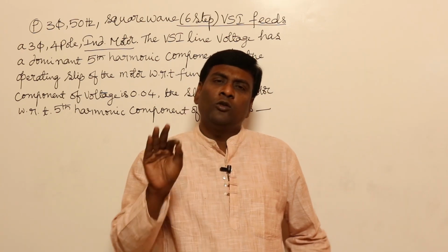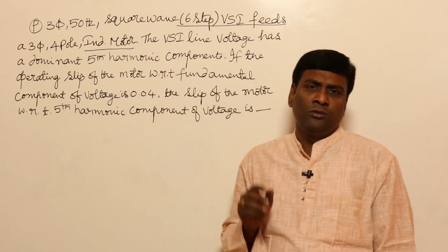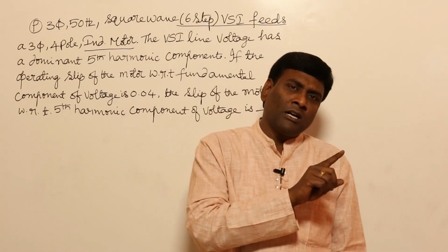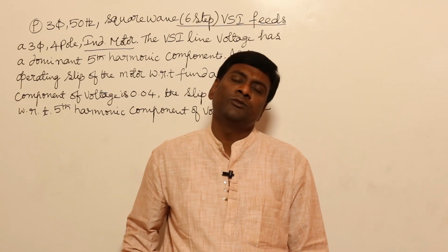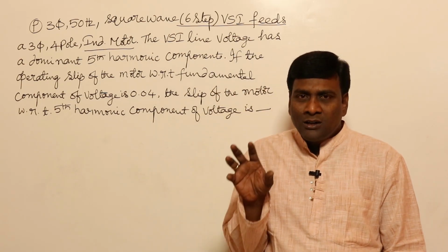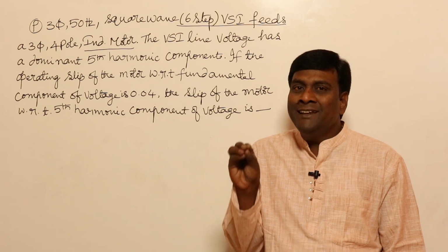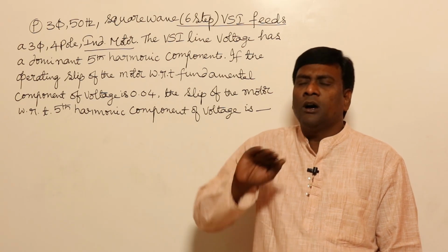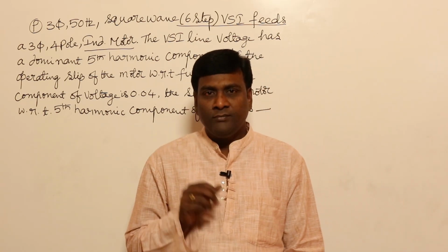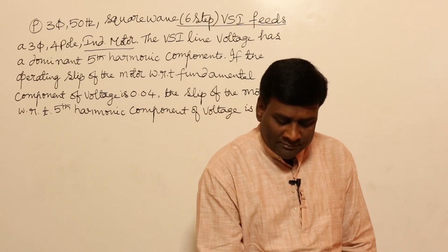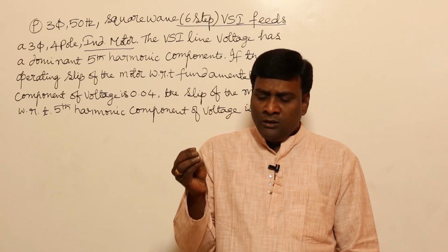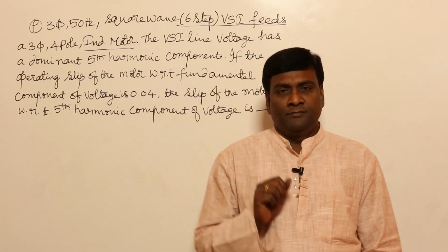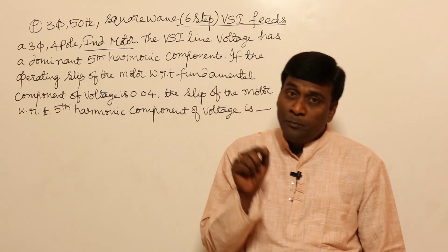So the underlying conclusion is very simple. In our previous sessions also, if you get any doubt, start from the induction motor starting analysis, you will come to know. So the rotor of my induction motor will interact and will develop torques with all harmonic components. Now, your books say fifth harmonic component Ns by 5, seventh harmonic component Ns by 7.